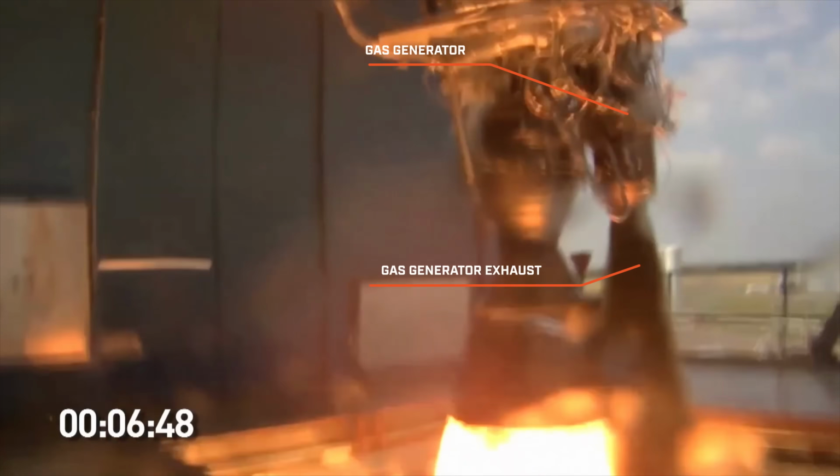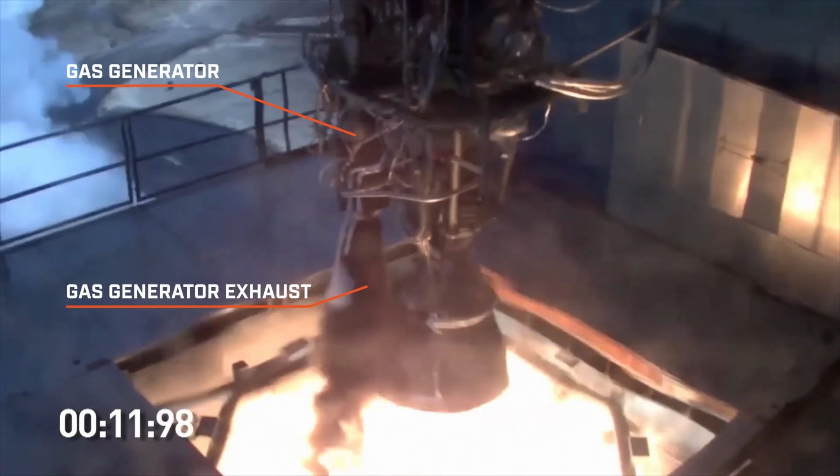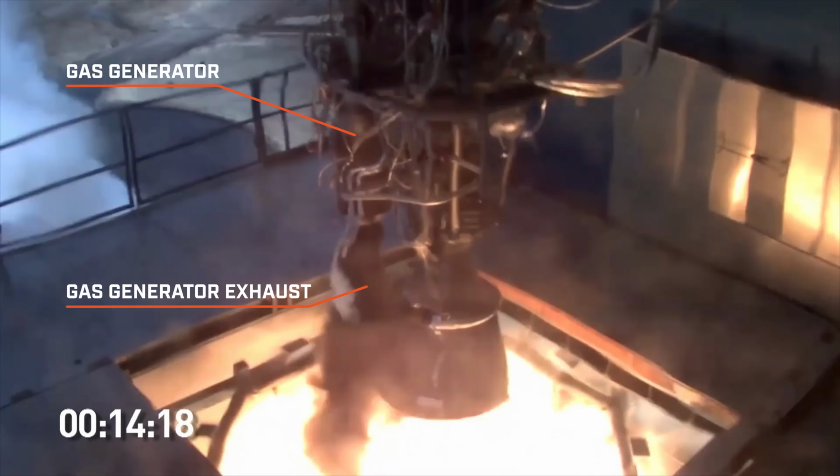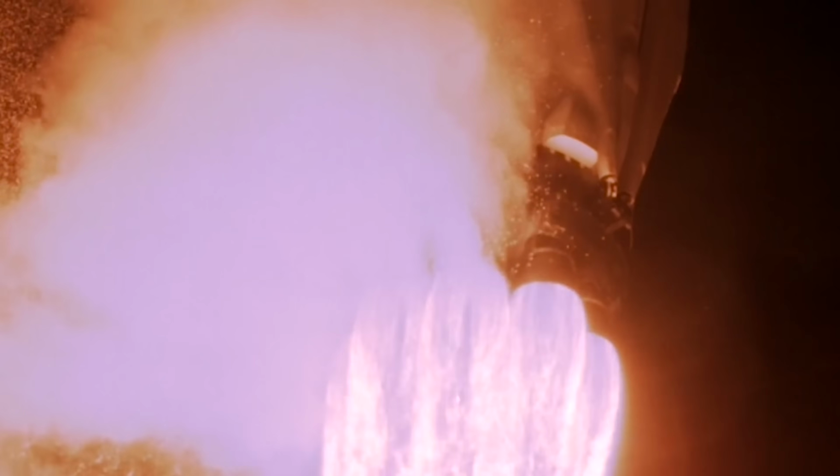The downside with the open cycle is that there's a ton of unburned fuel in the exhaust. See how dark and sooty the exhaust from the gas generator can be? That's unburnt fuel just being wasted and thrown away. So the open cycle wastes some of the propellant in order to power the pumps, but generally it's considered worth it because it is a relatively small amount of fuel compared to the amount of fuel used inside the combustion chamber.